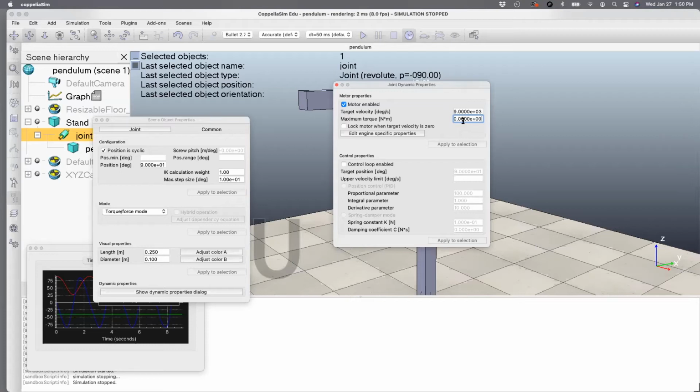The way this works is you cannot set a negative torque, you can only set a positive torque. So when you put a negative value, it actually rounds up to 0. If you put minus 2, it will be 0. So you are restricted to only a positive torque. Then how can you get this to stand at a minus 90 degrees position?